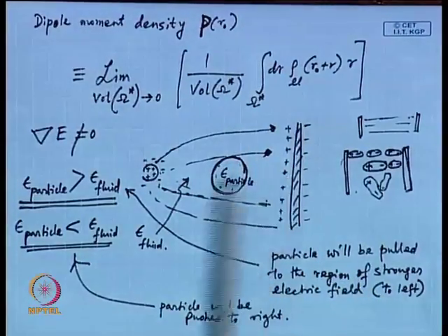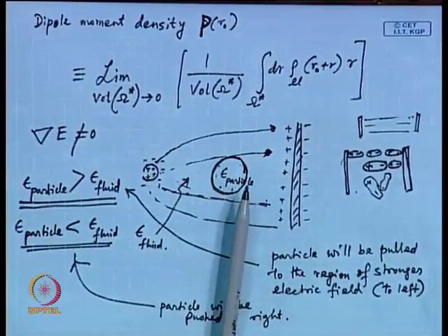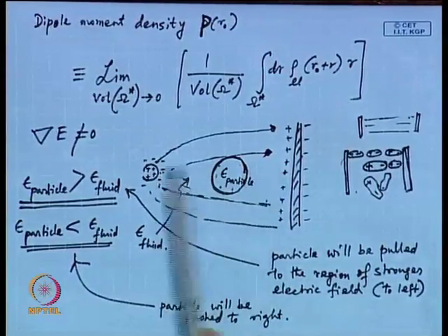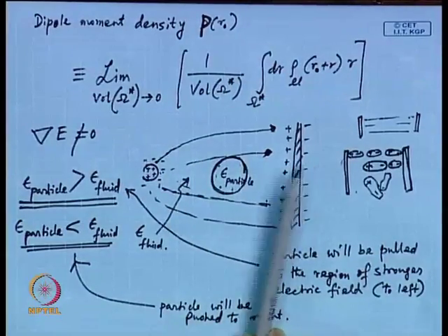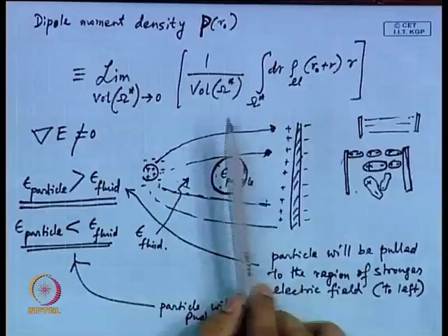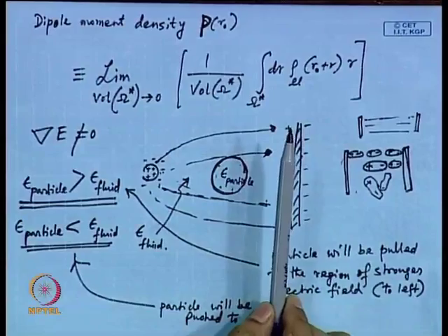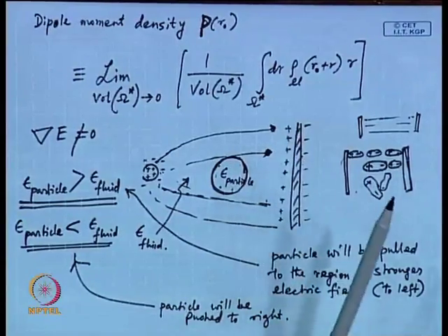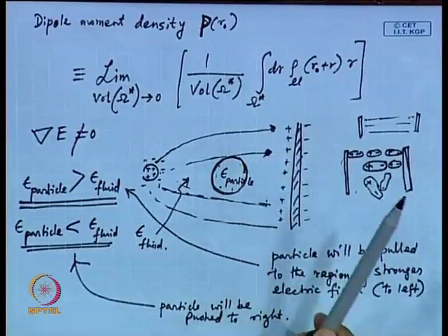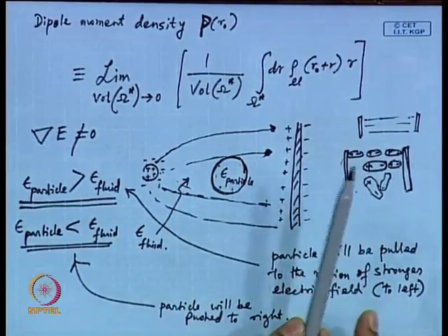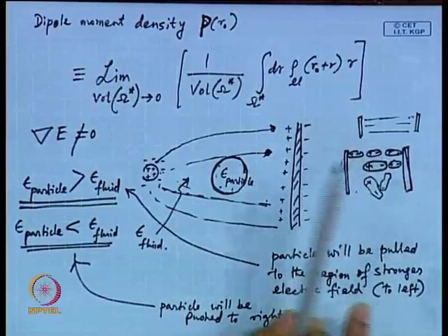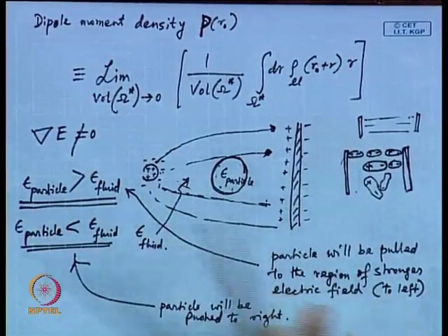Now, if you can align particles depending on their dielectric property, at various locations within this channel, then at the outlet, when you receive it, you can detect them, and against a pre-calibration you can find out for an unknown sample what all particles you have. That is one way of doing it, using this DEP in a field flow fractionation mode, which researchers have already studied.